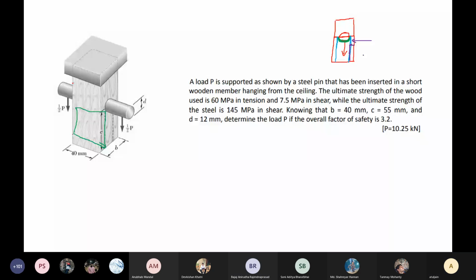But no. We are looking at, again, average shear stress. It is possible that in the region marked by the arrow, the value of the shear stress is low and then it is increasing. But in this course, we don't know how to calculate stress point by point. We're only looking at average values. So the entire surface we have to take. Got it, sir. Thanks, sir.